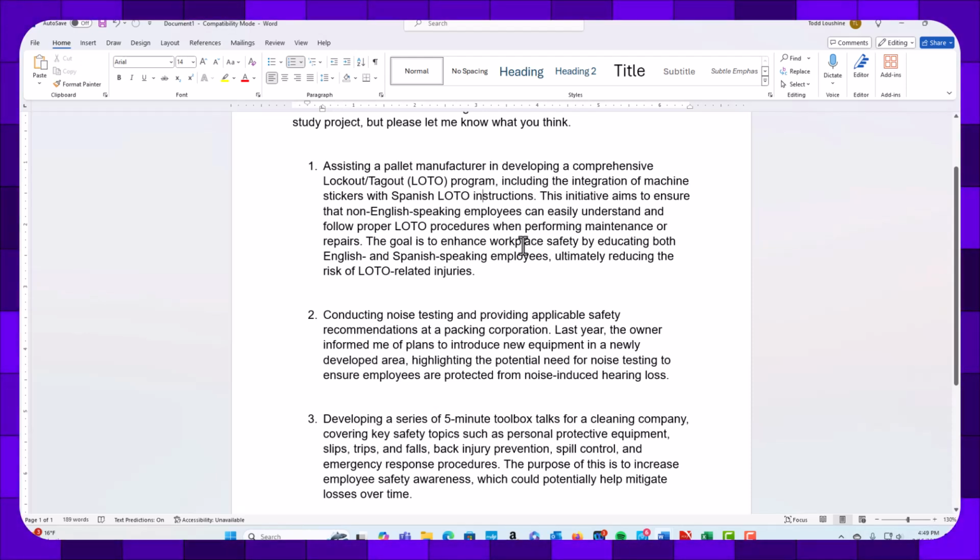And that is to identify the sources of energy, work with the maintenance and engineers to design a step-by-step process in which you can go through and close the proper valves, close the proper switches, put in blocking mechanisms, deactivate energy, or redirect it, isolate energy, isolate pressure, things like that. So that when you get in there and start working on it, it doesn't accidentally release, or the machine doesn't accidentally reactivate. Okay.